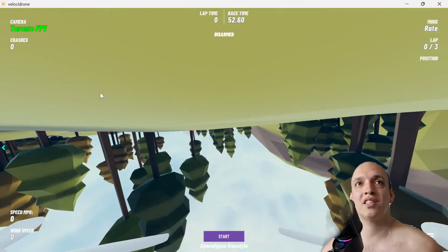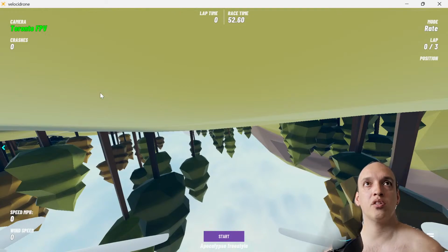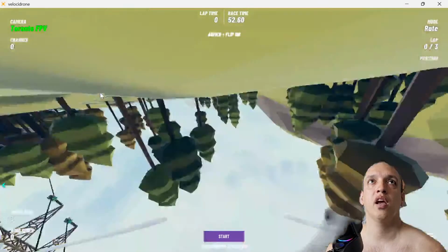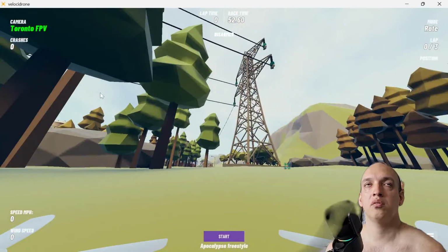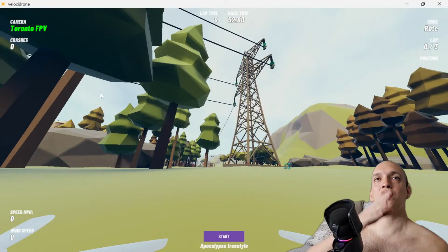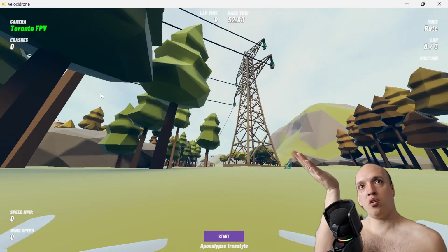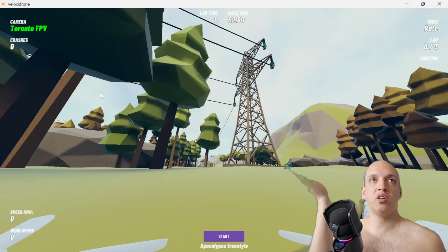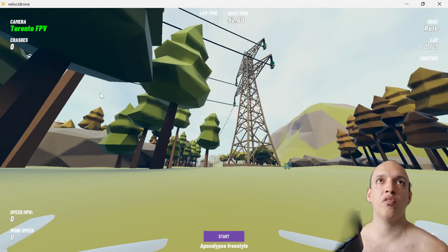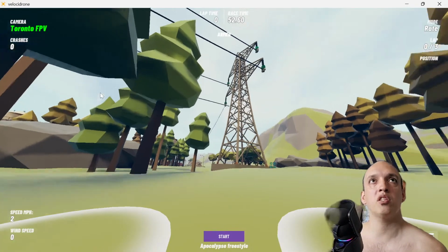So now let's say you're stuck here on the ground, and you want to turtle. So you activate turtle mode first, and then you arm it, and now you can push. So let's say you're tilted upside down to the right. You would turtle, and then move your joystick a little bit to the right to flip yourself over. And you can do it all. It's the same in the sim. The sim's a little bit more sensitive.